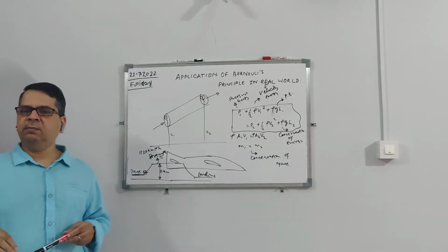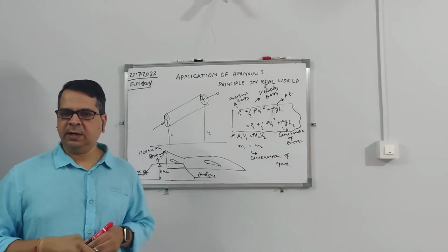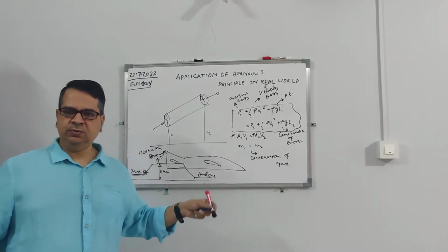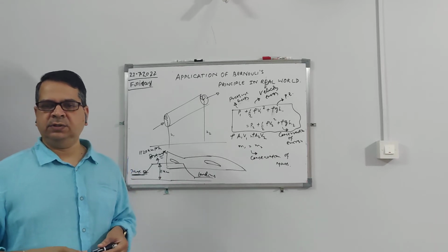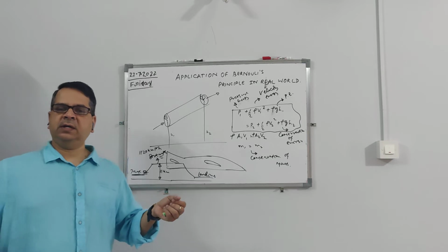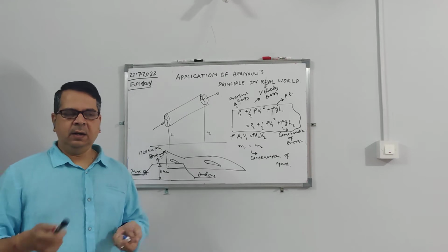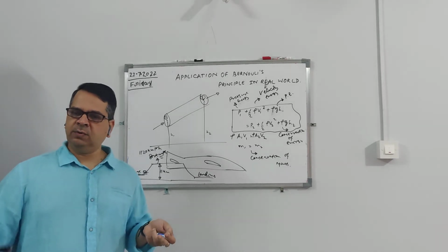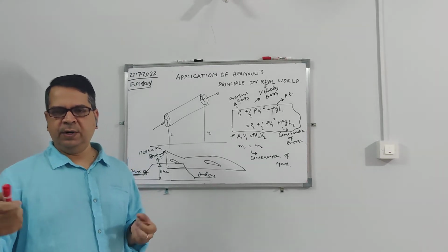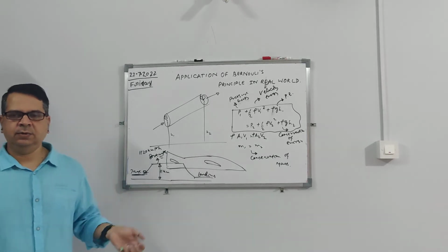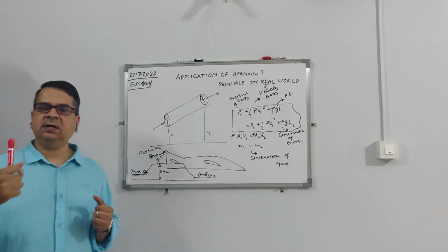There is a thumb rule. The aircraft structure, like the fuselage, wing and all, will also be 20 ton. Similarly, you are carrying some fuel in the aircraft, which will also be 20 ton. So one third, one third, one third. The passenger weight is called the payload, and the fuel is for operating the aircraft. Then you have the structure. So in total some 60 ton.